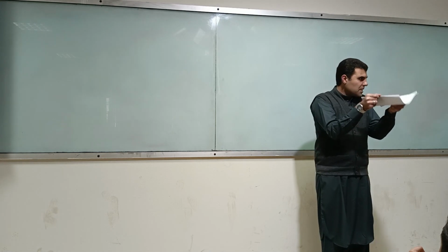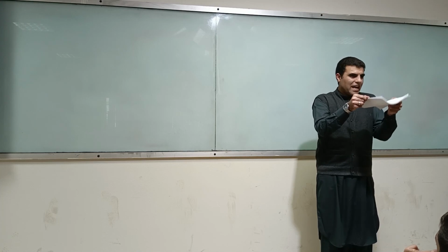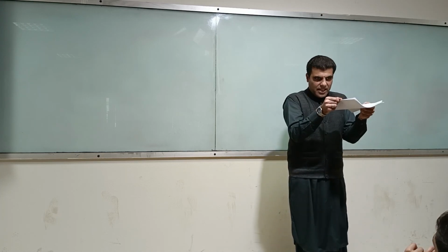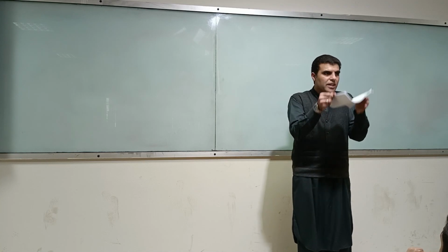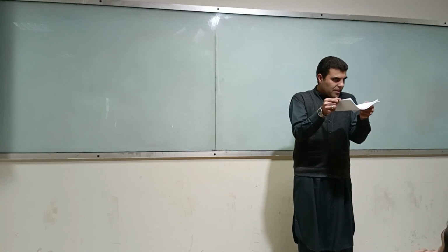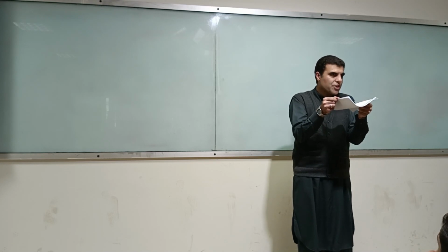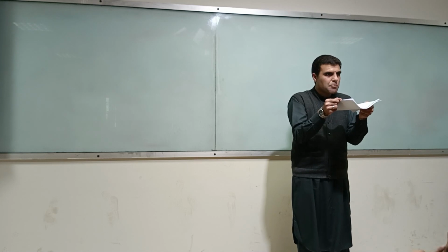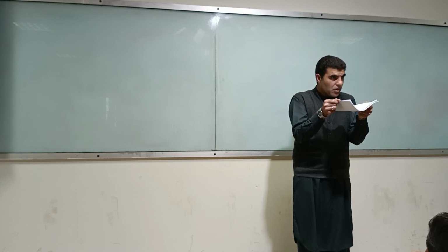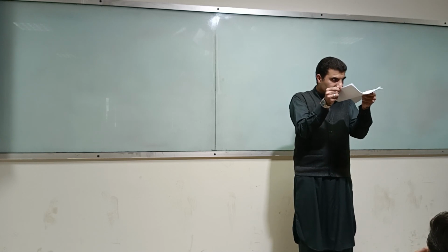Okay, so the property of my elastic curve is, imagine my left hand is point A and my right hand is point B. So at point A we have to work out the compatibility equation, or the equation of the elastic curve. So what is the equation of elastic curve at point A? The deflection is 0 and the rotation is 0.